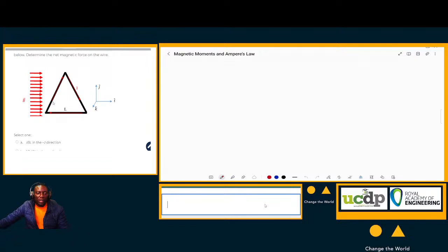For the perpendicular, the angle is 90 degrees, so that would be the angle. And if they are in the same sense, like the horizontal side here where we have L, there is no force that acts on that part of the conductor, because it is parallel. It's because of cos 90, which is 0. So in this case, what we are considering is the angle between the perpendicular to the wire, or the conductor, and the field itself.